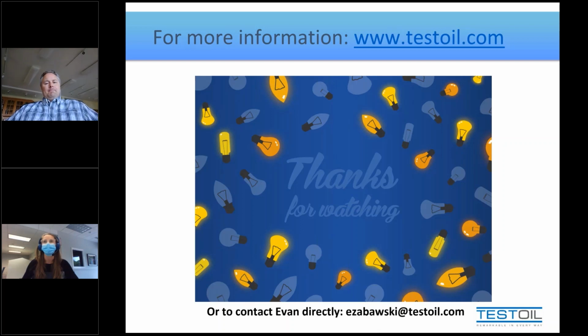Our next question was, sometimes samples are taken a month beforehand, so are they still good for analysis? It sounds like you kind of answered that with the maritime question, that they will still be good for analysis. You can just take precautions by keeping it in a dark, cool space, and the laboratory also takes precautions and agitates samples as they come in. We don't encourage this behavior of letting samples sit for a month, but if logistics dictates that they have or will, it's not the end of the world.